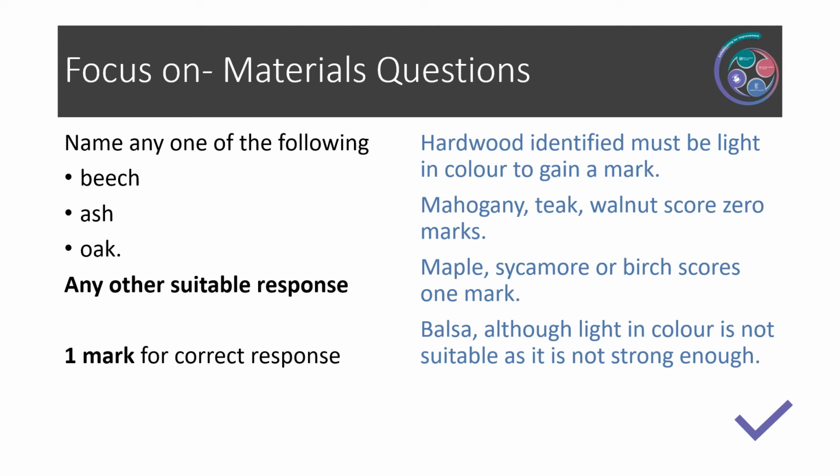Other suitable hardwoods are maple, sycamore or birch, which would also gain 1 mark. Balsa wood would not be a suitable answer because although it is light in colour, it is very weak and is not strong enough for the purpose shown.